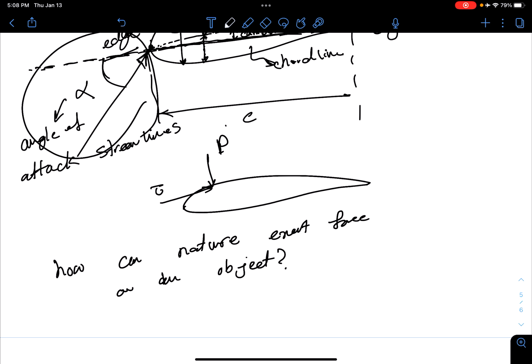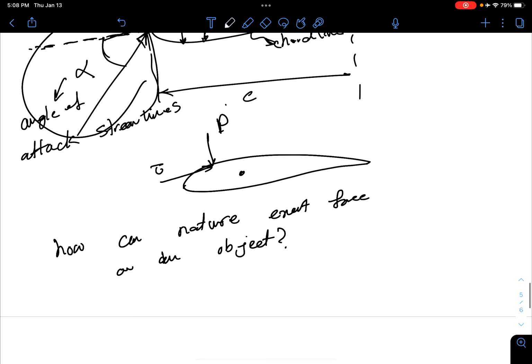So we can combine all of these together to a resultant force R and also a resultant moment M, right? Why do we have the resultant moment? I assume you understand why we have the resultant force. We just combine all of the forces. These are vectors. We just add all of the vectors together, a resultant force, right? And this is a pressure distribution, so we have to take the integral. Right? We have to integrate. It is not a simple addition. But why do we have the moment?